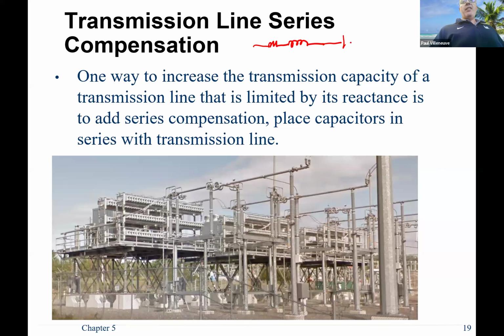Then over here, you have the series compensator, and that series capacitor only exists there. And then across it, you have a bypass switch where you can completely bypass the series compensator. So if it's got a problem, you can short circuit it out, and then you can open it up and do maintenance. Because you never want to have a system out there that takes your whole system down.